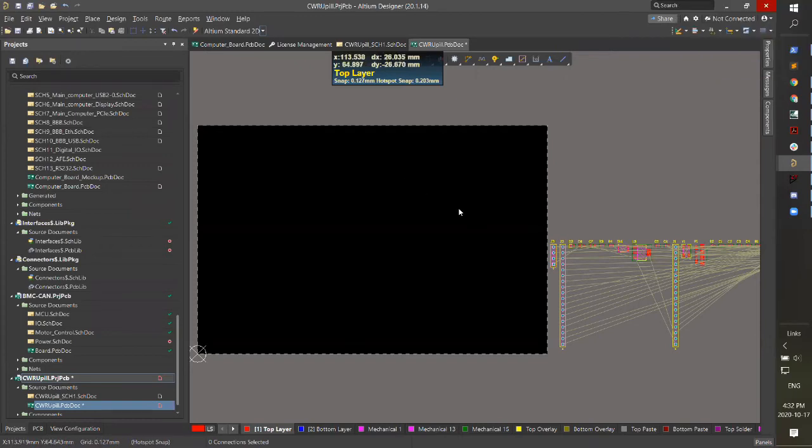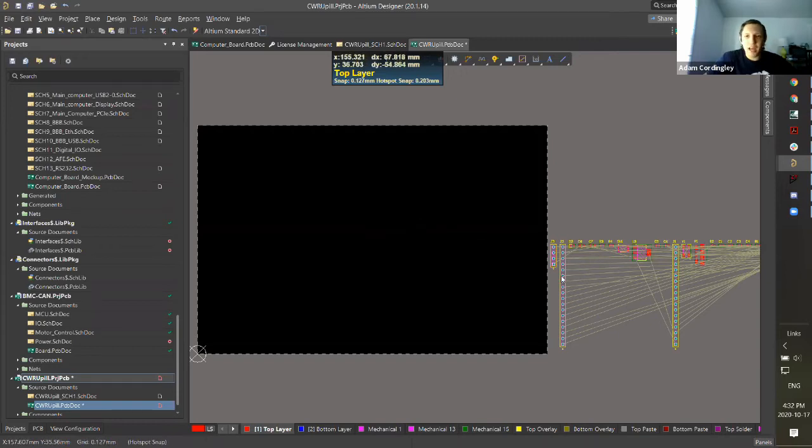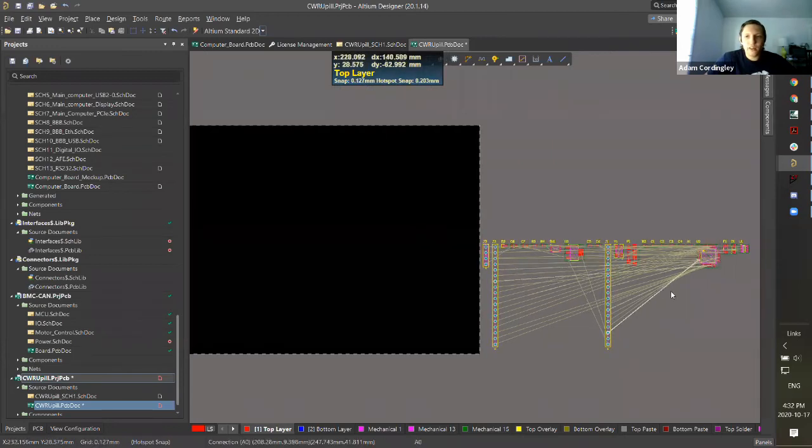Is auto routing just really inefficient? I don't think so. I think it just produces sort of bad results. The results aren't particularly good. And yeah, there are certain inefficiencies, depending on how you want to define efficiency. It won't necessarily make the shortest path. It won't necessarily prioritize certain nets to be shorter than other nets.